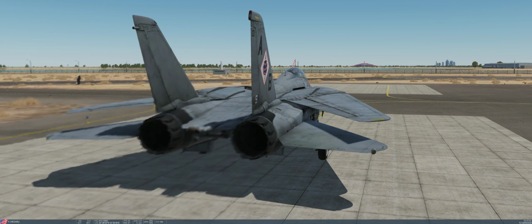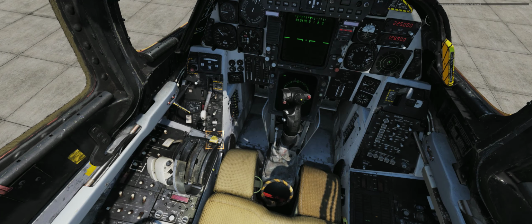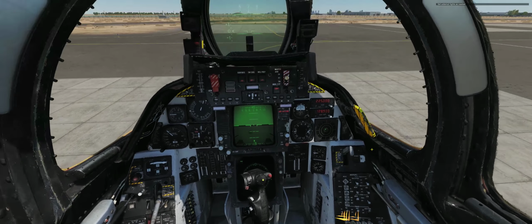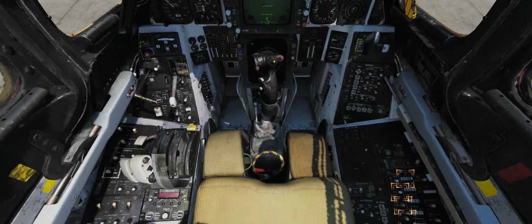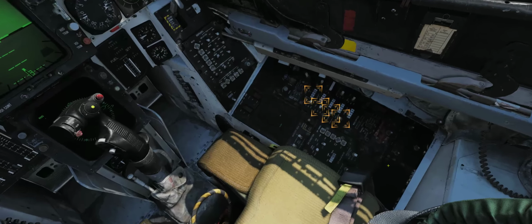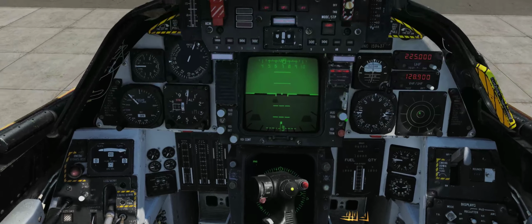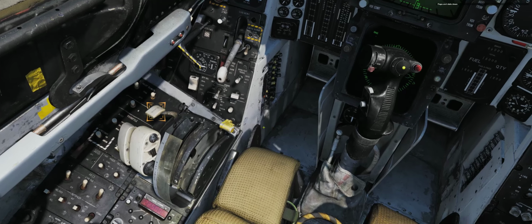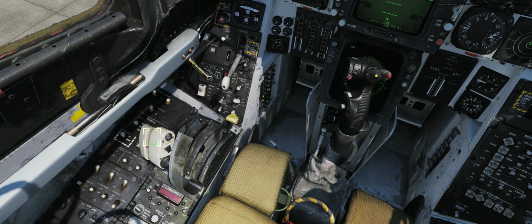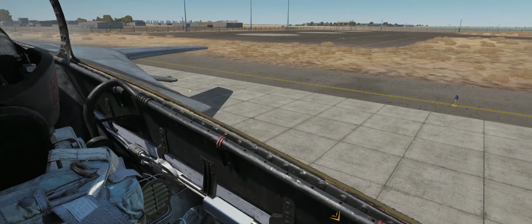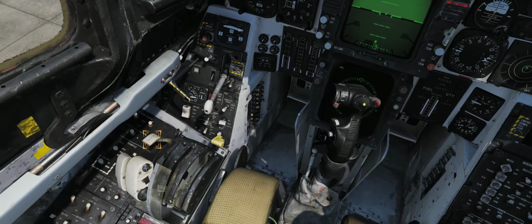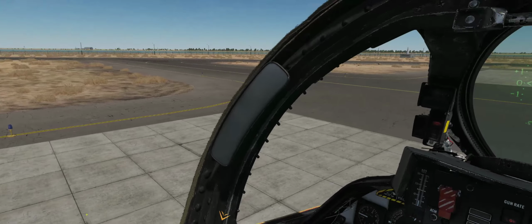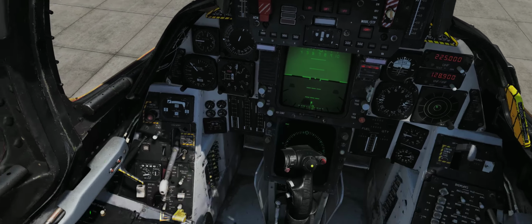Extend and retract refuel probe. Emergency wing sweep handle to full forward. Set external lights according to the situation. Verify flaps and slats operation and then down. Flight controls wipeout.